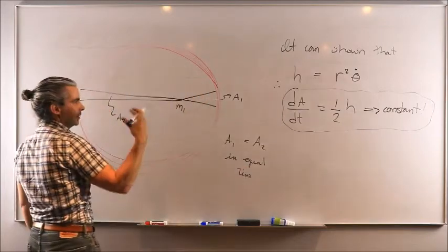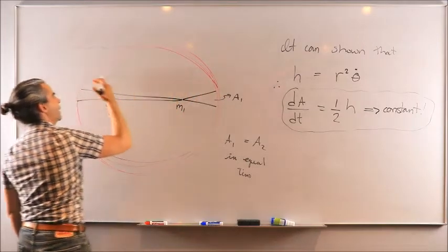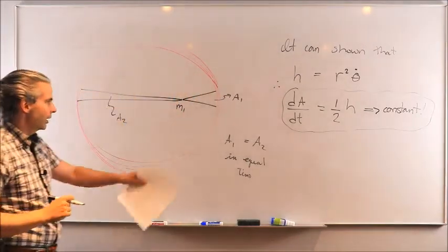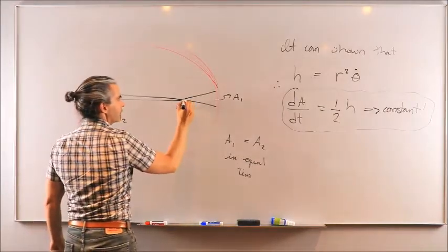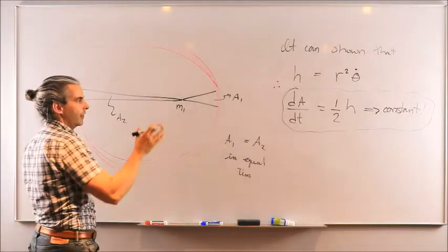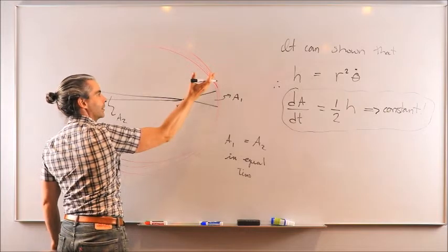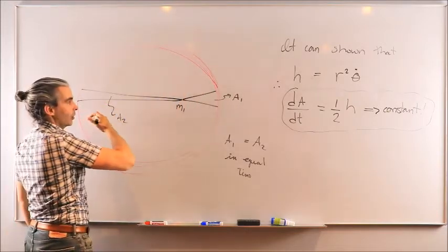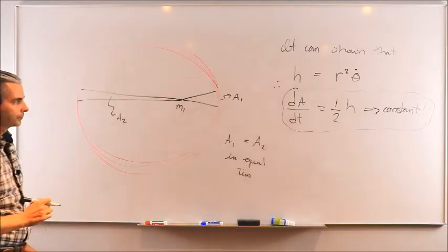in equal time, obviously. So pretend this is 5 seconds here. This is the area you get. In 5 seconds over there, you sweep out A2. Well, if you want A1 to equal A2, that means that the position vector better speed up here, such that in 5 seconds you cover a greater amount of true anomaly than you would in 5 seconds near the apogee. Otherwise, this wouldn't be large enough to be equal to A2.